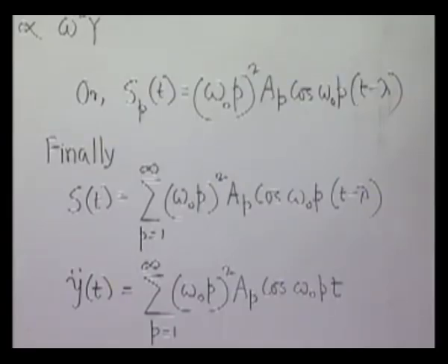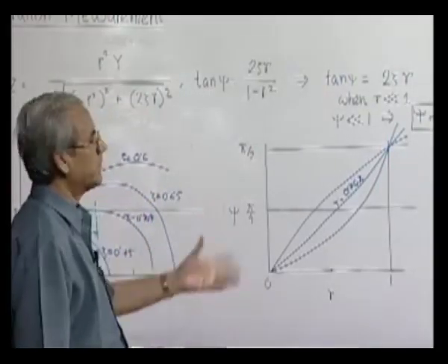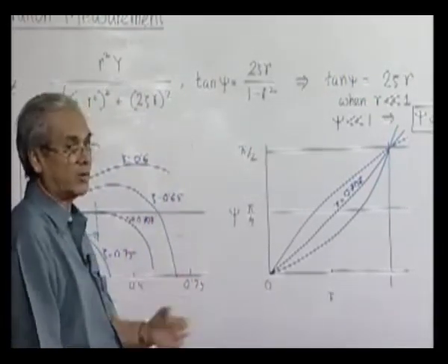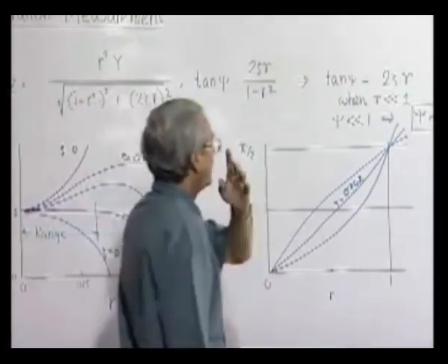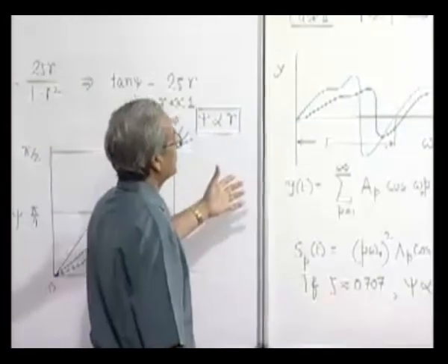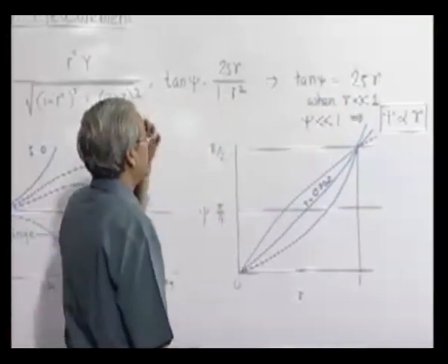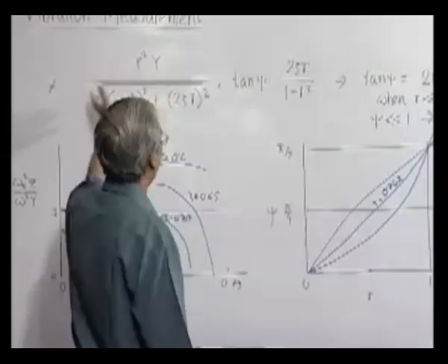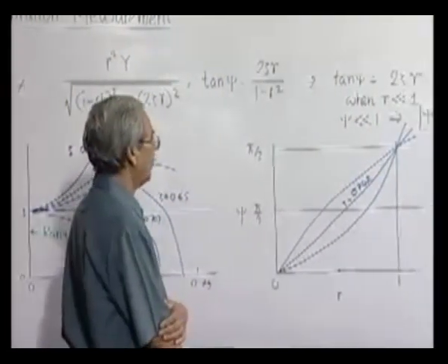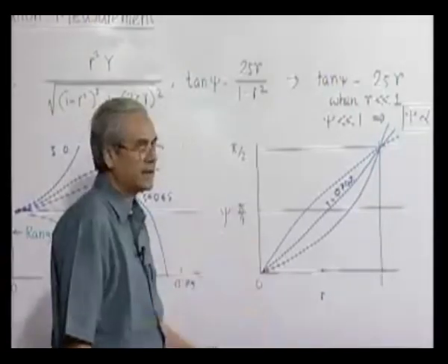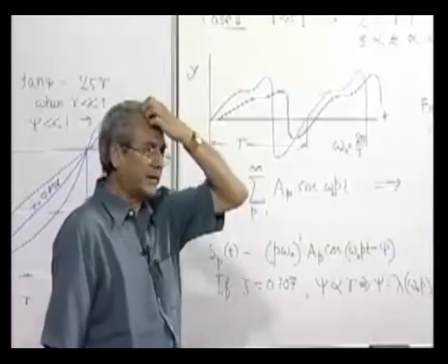So therefore we find that this seismic type of pickup can be primarily of two types. They are both contact type pickups, as you can see, and they are both passive, that means they do not require any outside power source. In the one extreme case, when the natural frequency of the system is very low, it is treated as a velocity meter, where the voltage is generated by electromagnetic induction.